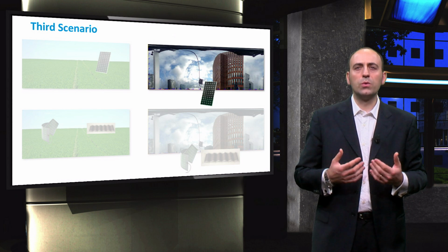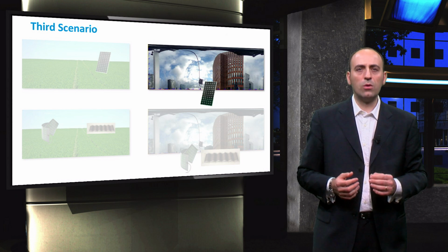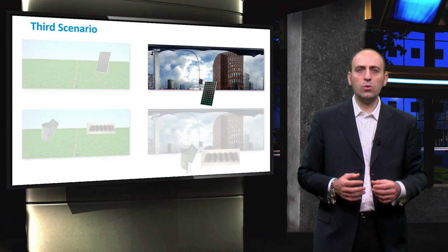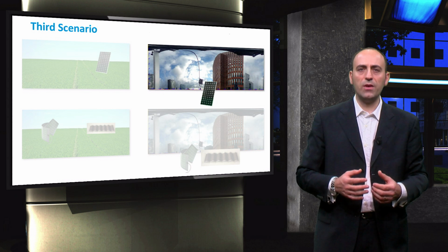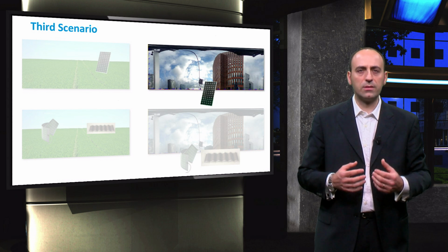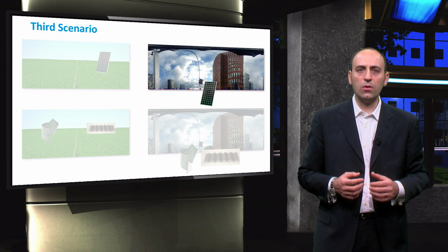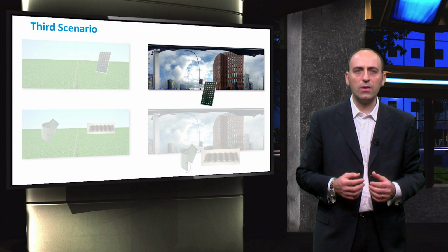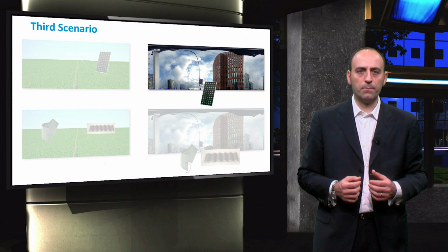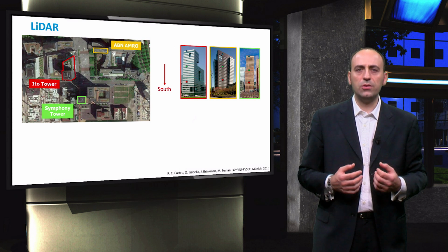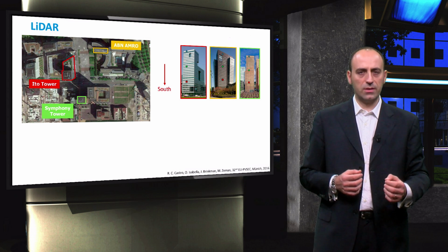For this, I'm going to explain to you about an irradiance modeling approach based on the use of LIDAR. The use of such an approach improves upon the existing options available when simulating complex surrounding environments. It combines the advantages of an on-site location survey method and a remote assessment survey. As you know, LIDAR is a surveying method that uses laser light to measure distances.